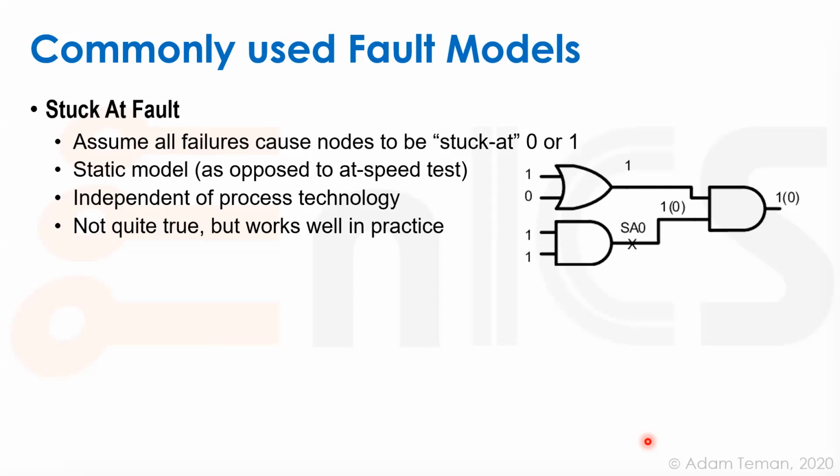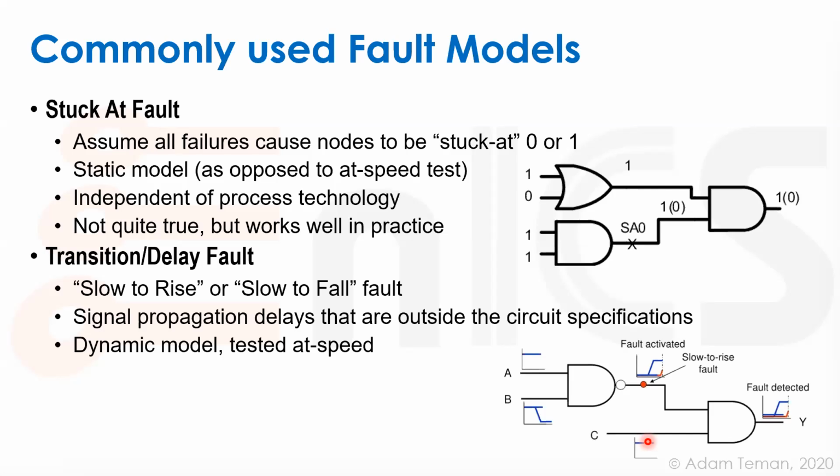It's a static model, which means that it's independent of technology. It doesn't have anything to do with the speed, with the timing of our circuit. It's not this dynamic type of a model. It's completely static. It is not a real model, okay? It covers, I would say, a small percentage of the actual defects that are there, but in practice, it works really well. It catches a lot of the errors, and it's basically the only one that is in real use, not 100%, because the other one that's quite commonly used is this transition delay fault, and that's newly used.